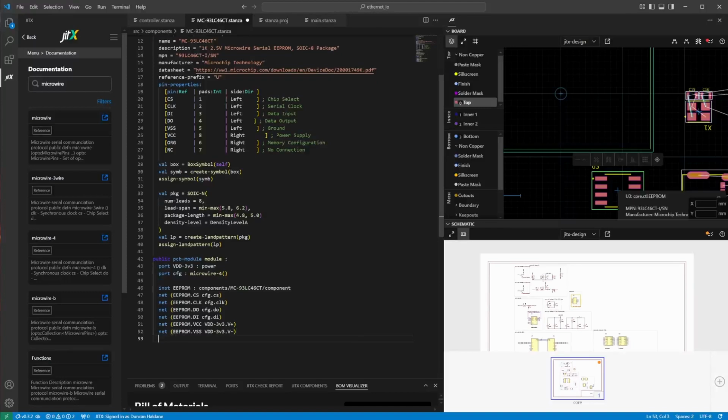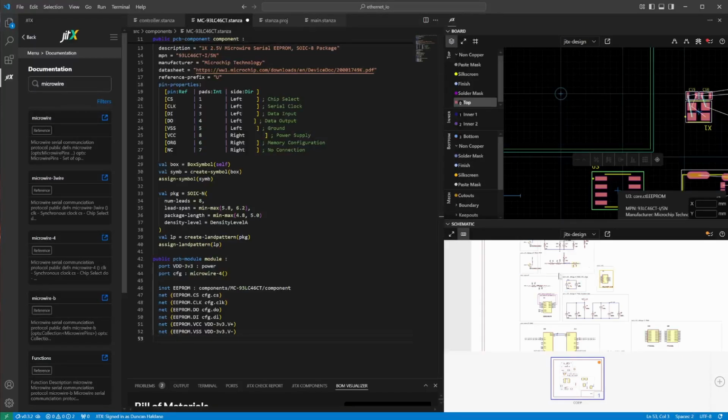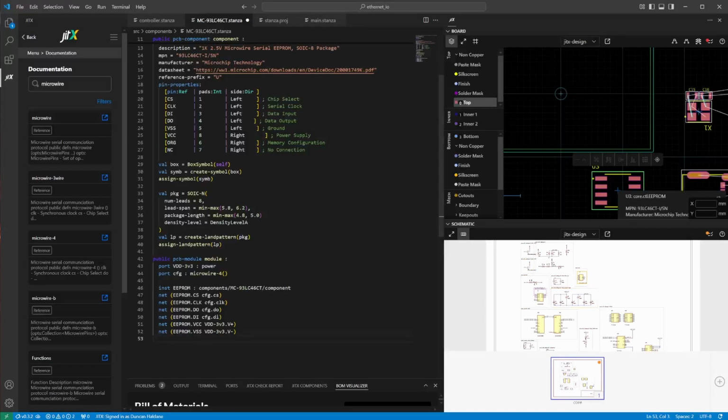Okay, so a little repetitive, but it's actually a really big advantage to be able to put custom circuitry inside a subcircuit and then wrap it with standardized bundles like power and microwire. You get a lot of reuse and ability to swap out this circuit for something else later. To finish this circuit, we need a pull-up resistor for the ORG pin and a bypass capacitor. To add those, we'll show one last way of adding parts, and that's to use parametric functions to automate your supply chain. We're going to call out what parameters are important, and then use automation to choose parts automatically. And this is what has been used to generate the vast majority of the resistors and capacitors in this design.